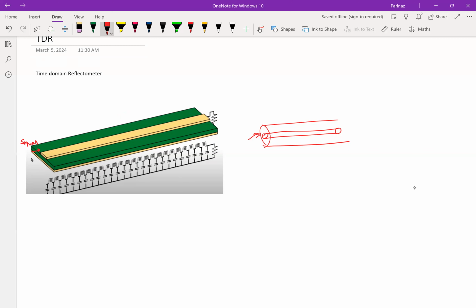It's going forward, right? If you design this transmission line to have an impedance of 50 ohm, and by that we mean that if the signal looks at this point, right at this point, and sees a voltage and a current going this way, for example, if it divides that voltage by that current, it would see 50 ohm over this line.